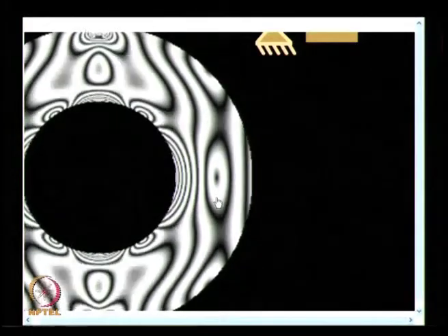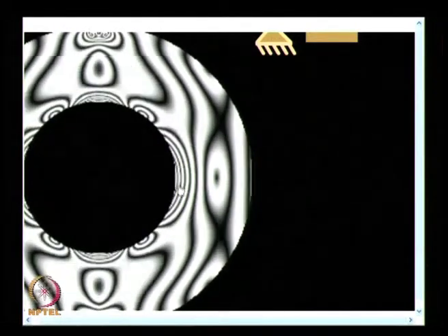One of the aspects I discussed was, in a plane polariscope, suppose you are given only a monochromatic light source, and then you had identified the difference between an isoclinic and isochromatic fringe field. I said if you have polarizer and analyzer crossed, if I rotate them, isoclinics will move. On the other hand, if I change the load, isochromatics will move, the exception is zeroth fringe order, and that you see here. When the load is increased, the zeroth fringe order remains as such.